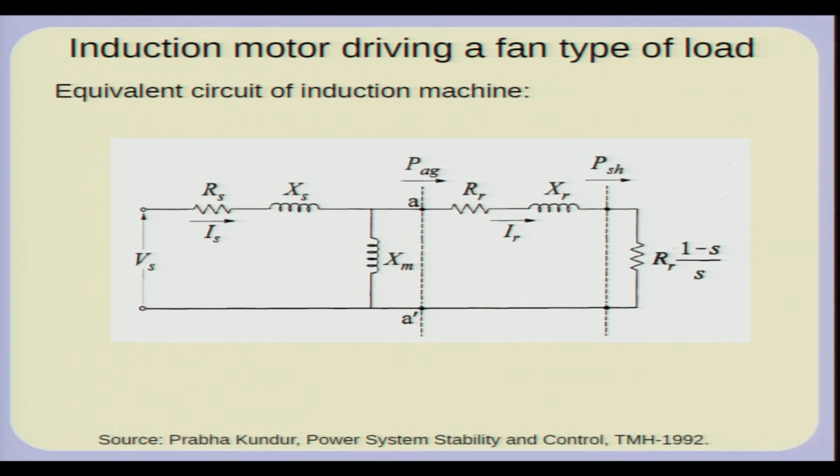The most important thing is that it is like a transformer, but the equivalent rotor resistance which the stator winding sees is a function of the slip. So, the so called loss here is not really a heating loss, it is actually used to generate torque.